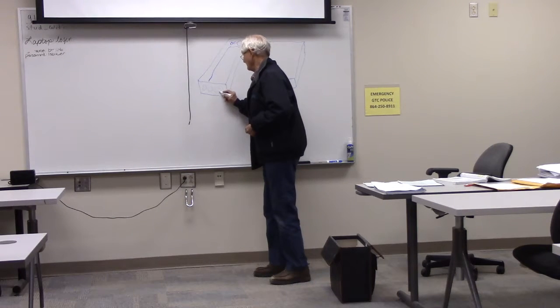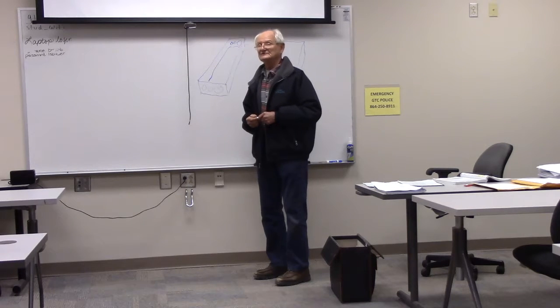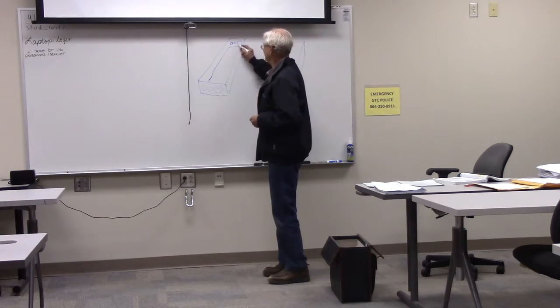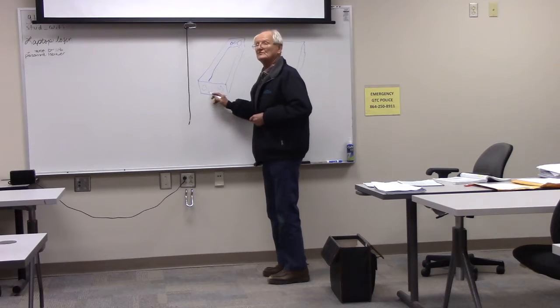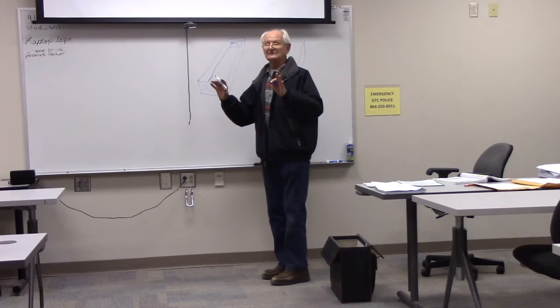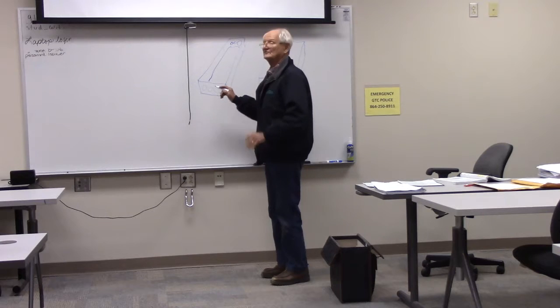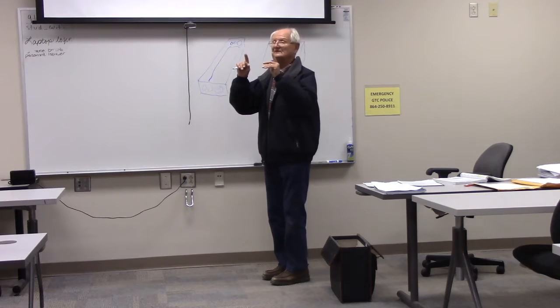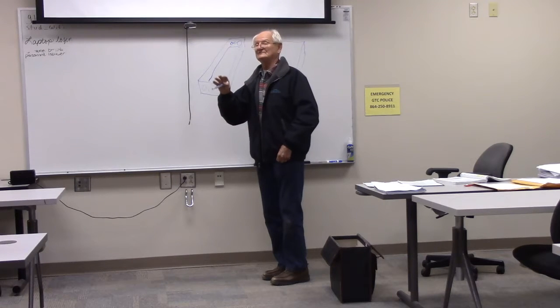The diameter of the largest raceway is 3 inches. All right, so 3 inches, so 8 times what? 3. All right, and that is 24. 24 inches. So this box has to be 24 inches long. The two 1-inch conduits don't add to it. All right, you've got it on a straight pull. It's 8 times the diameter of the largest conduit going into it.